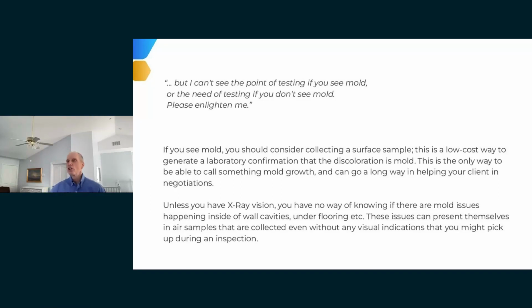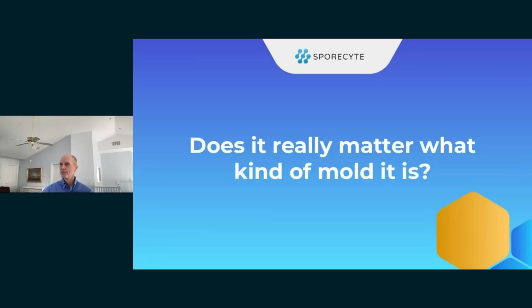Let's see. One question that we get sometimes is, if there's mold in between the walls, will the air sample find it? And the reality is, probably not, because we've got to be in the active air environment to find mold in the air. There could be occasions where there are some cracks in the wall or something, even microscopic cracks, where mold can get through from the outside of the building and inside the building. But I would definitely say you can't guarantee that. I would say rarely would mold inside a wall and an air sample not pick that up.